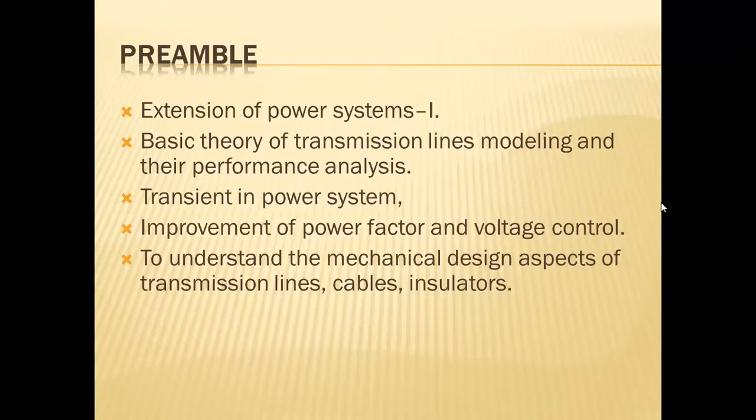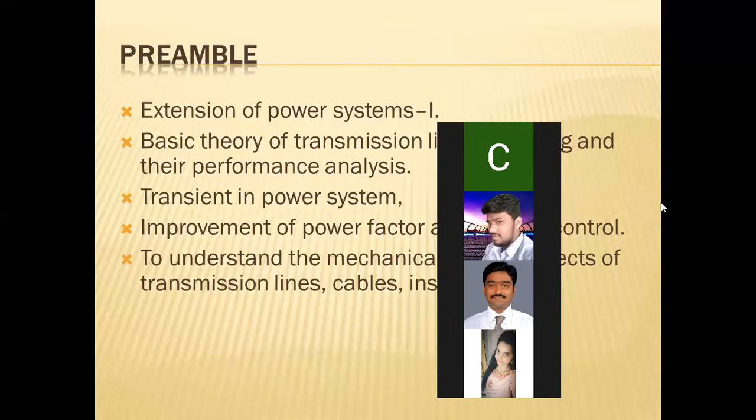The difference between transmission lines and conductors: transmission lines are overhead lines and cables. Overhead lines are bare conductors suspended above the surface of the earth, and the conductors are spaced with certain distance between them. So interconductor insulation and insulation to earth is provided by air itself. Whereas a cable is a bundled conductor.